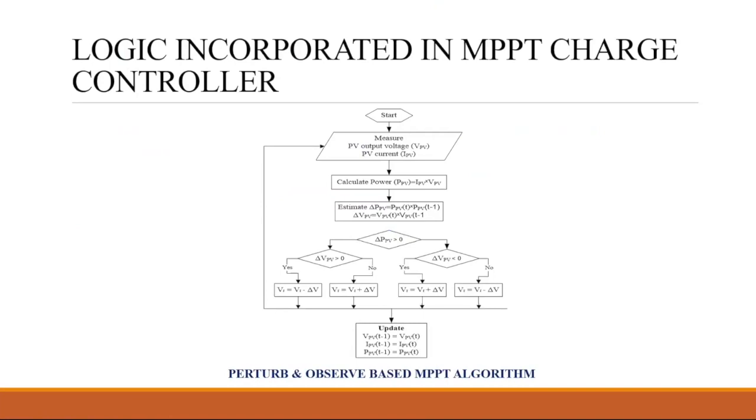So again, come towards that curve that we drew. Power, voltage. What is this point called? Anyone? Maximum power point, right? If the point is maximum, what will be the power? Maximum. And what will be the voltage? Again, maximum. So this is the maximum power point voltage, VMPP.